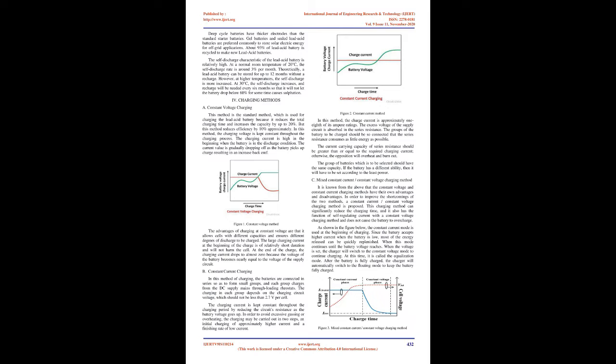Wind power. Wind turbines generate electricity when air flows. Current-day turbines range from around 600 kilowatts to 5 MW of rated power. Since the power output is a function of the cube of the wind speed, it increases rapidly with an increase in available wind velocity. Recent advancements have led to aerofoil wind turbines, which are more efficient due to a better aerodynamic structure. B. Solar power.